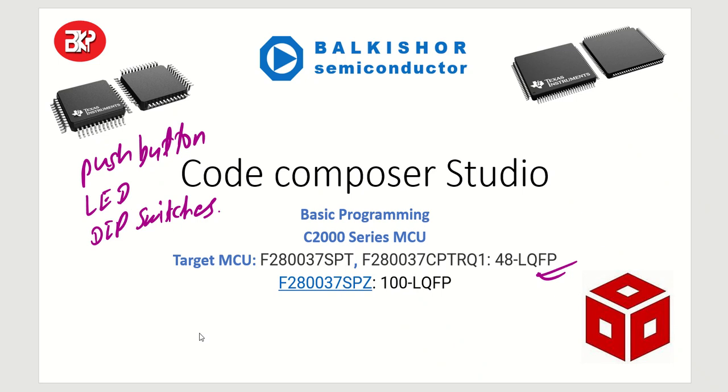Namaskar, my dear friends. Let us continue the coding on Code Composer Studio for C2000 series microcontroller. So we were seeing F280037 SPT, that is 48 pin LQFP package. What we'll do is we'll try to complete, we have already completed LED, push buttons, LEDs. Now we'll try to complete push buttons and dip switches pin configuration in our circuit.